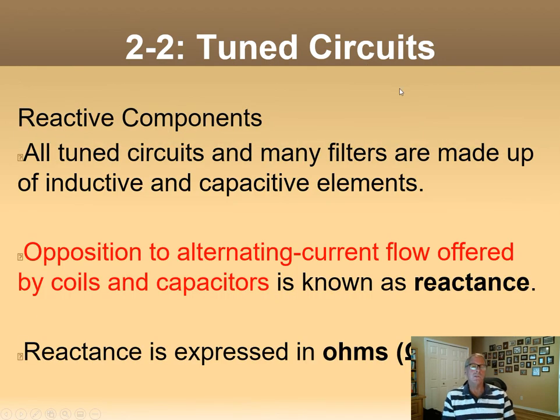So reactive components are basically components that have reactance, meaning an impedance, that is a frequency sensitive resistance. I like to express reactance that way, as a frequency sensitive resistance, meaning the resistance goes up or down with frequency depending on if it's a capacitive reactance or inductive reactance.